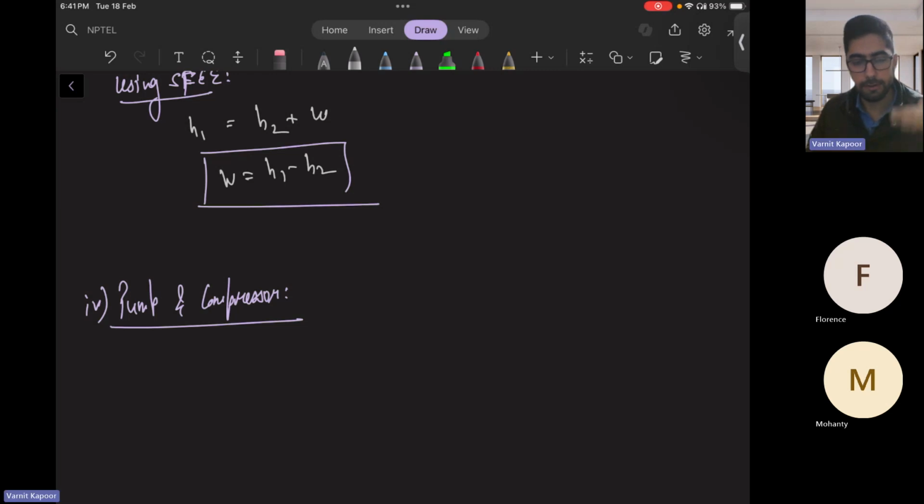Okay, so energy is transferred from the rotor to the working fluid by increasing the potential head. So a pump is generally used to handle liquids and is used to increase the pressure of the working fluid. Only the pressure. Whereas a compressor is used to increase the pressure as well as temperature. So in the pump, if you switch on the motor at your home, whatever the temperature is at the inlet of the pump and in the tank which you stored at the outlet, both have the same temperature. Okay, it's not like you switched on the pump and the water got heated.